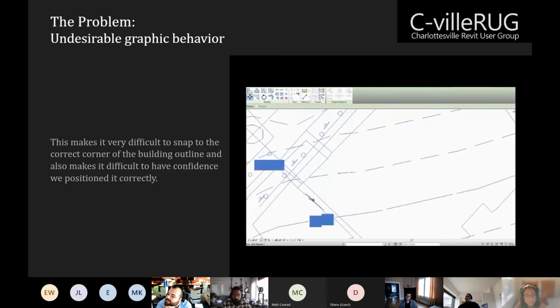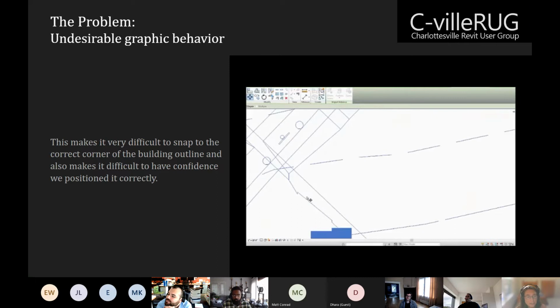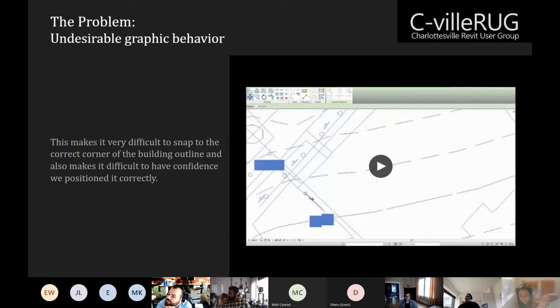So when we try to move that CAD file and we try to snap to an endpoint, you can see where that pink square snap is, and it's indicating that line just below it. So the line below it was getting highlighted, but the snap point for it was far away from it. So what you're seeing on the screen isn't reality, but Revit still knows what reality is. So you have to just blindly trust that whatever Revit is snapping to is actually the right point.